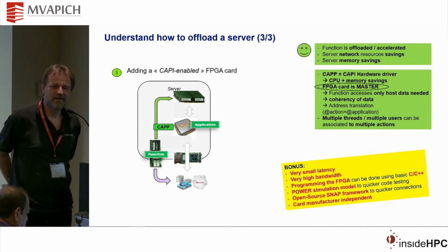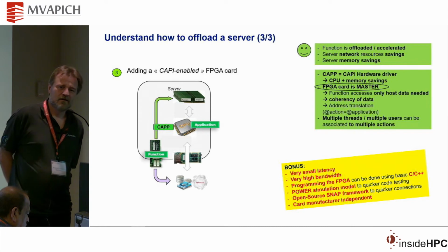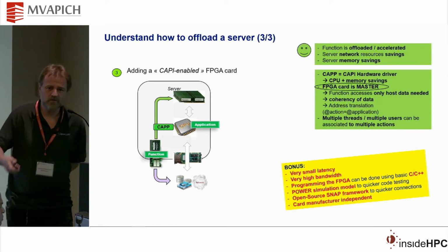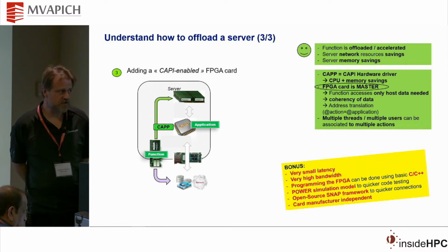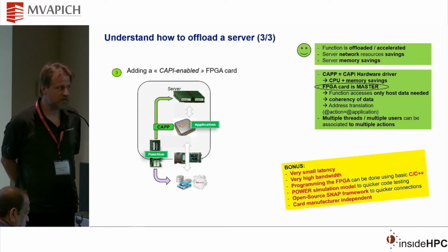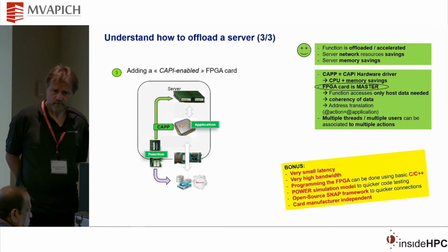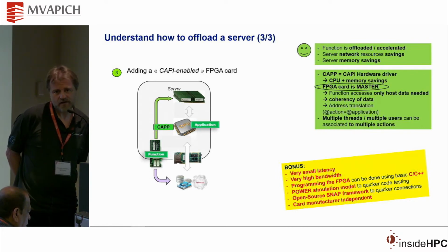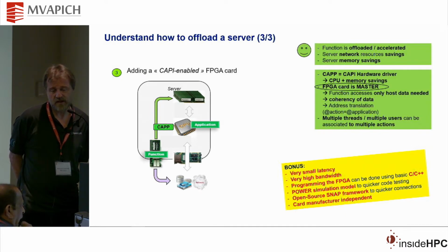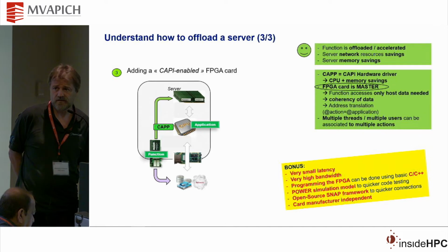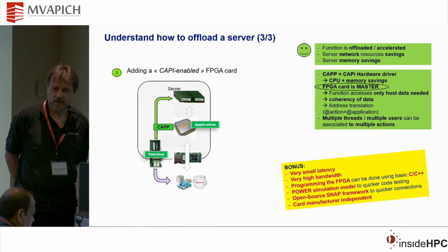So you're saying that if I've got an existing PCI Express FPGA card, it will work if my motherboard supports it? So the question, your first name is? Nick. Nick's question is, I do have an FPGA board PCI Express in my lab. If I plug it into a Power server, will it work? So if it's a Xilinx component, there is chance it works. If it's an old Xilinx component, it will probably work in CAPI 1 mode in P8 servers. If it's generation Virtex Plus, that is the I/O is faster, you might have the chance it will work on a Power 9 in CAPI 2 mode.